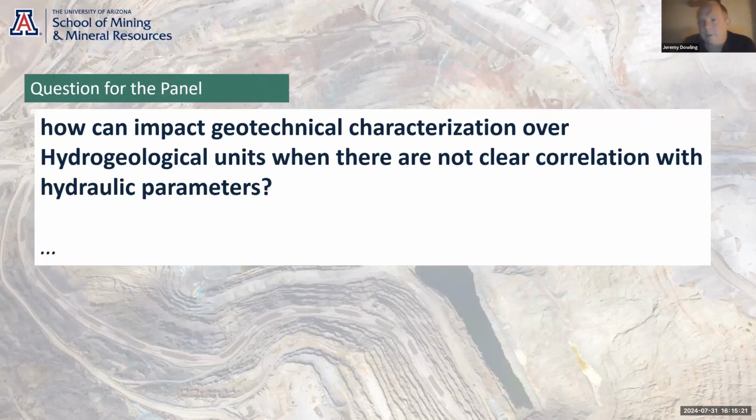If you've got geotechnical domains in a pit slope that are weaker or higher risk, creating potential impact to the slope design, limiting the slope design, or are potentially sensitive to pore pressure, then you have to characterize those geotechnical domains hydrogeologically, right?